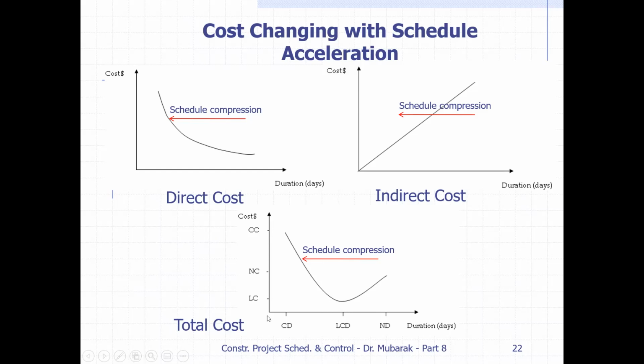So the most suitable time, least cost duration. At this point, if we shorten the duration, cost will increase. If we increase the duration, cost will also increase. So we are going to find the optimum time where the project gives the lowest cost.